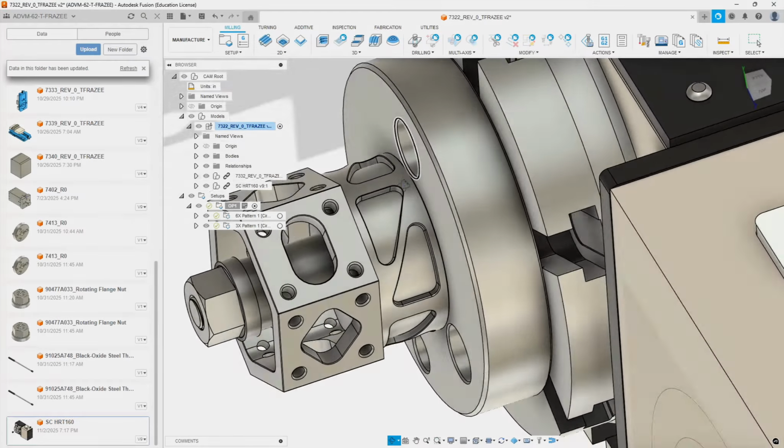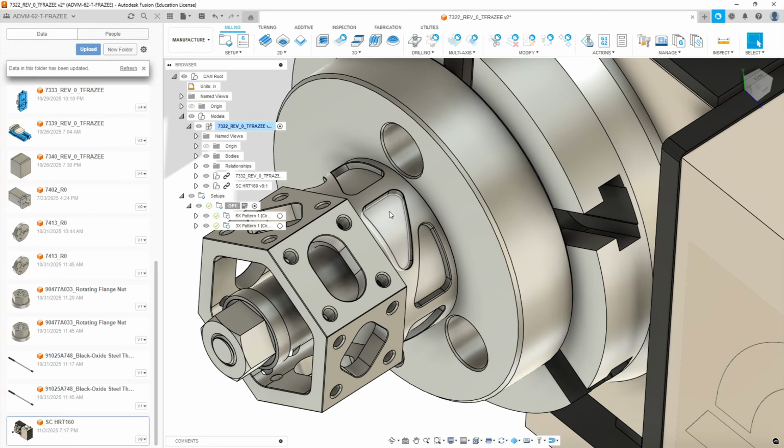Realized at recording of this is that we will need to make an adjustment to the tool library. Your current tool library has the 1/4 inch end mill a little bit too short. It might rub on this chamfer here. So as of the recording date, what we need to do is go to your library,